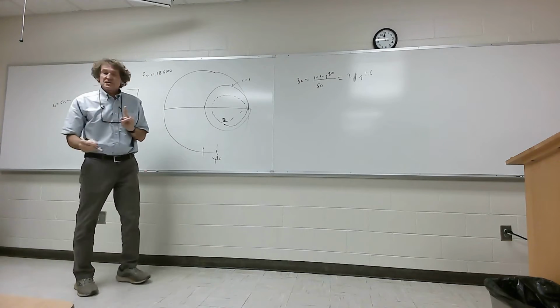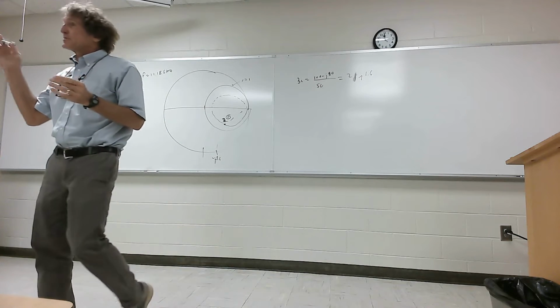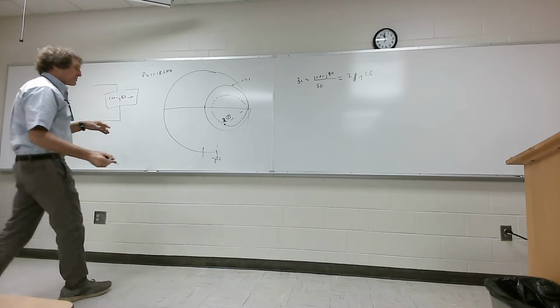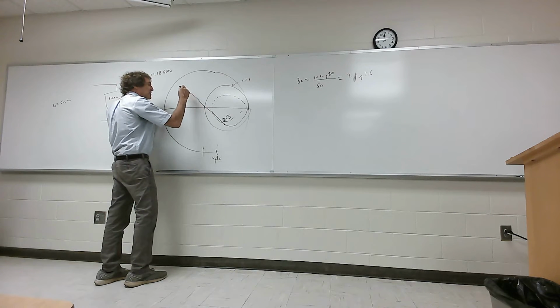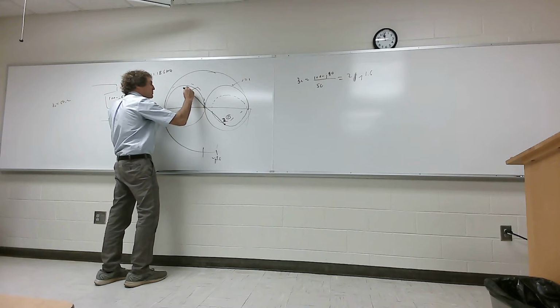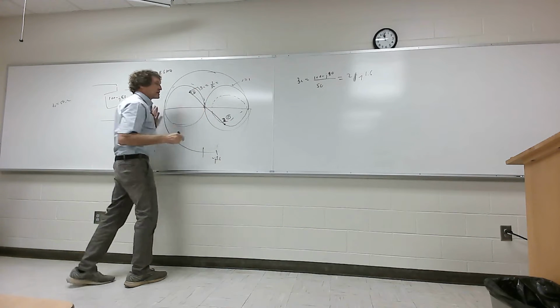When you do this on a Smith chart, label that as point 1 and circle it, so I know where you start. Because half the time, I don't know what you're doing. I'll see lines drawn this way and that way. But you all follow me, that's the first point. Now, it's inside the one circle, correct? We have to go to the admittance domain. So we go right through it to the conjugate point, over here. And then I better draw my rotated circle. This is kind of a lousy looking circle, but you get the idea. And this is going to be yL, that's 0.2. yL here is 1 over zL. Can somebody see that?